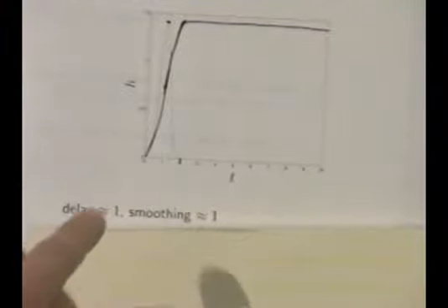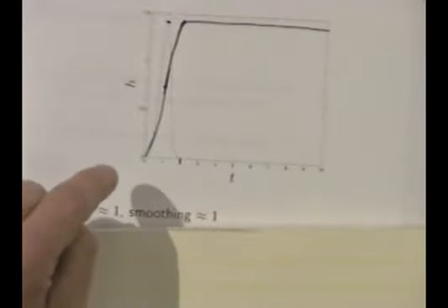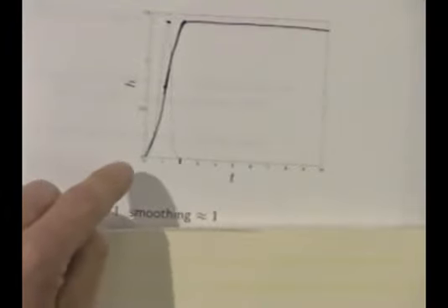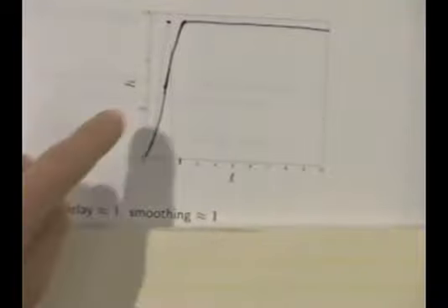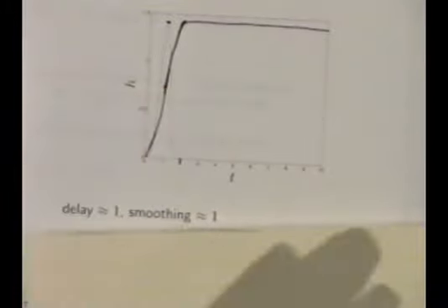And from the step response, again, you see things here. You see that the delay is about, well, it depends how you define the delay. If you want to define the delay as the time it takes before the voltage gets to its final level, it's about 2 seconds. If you define the delay as the time it takes to get halfway, the delay is about 1 second.